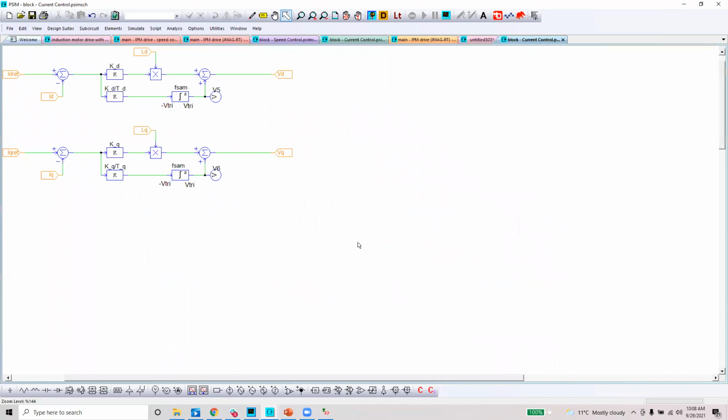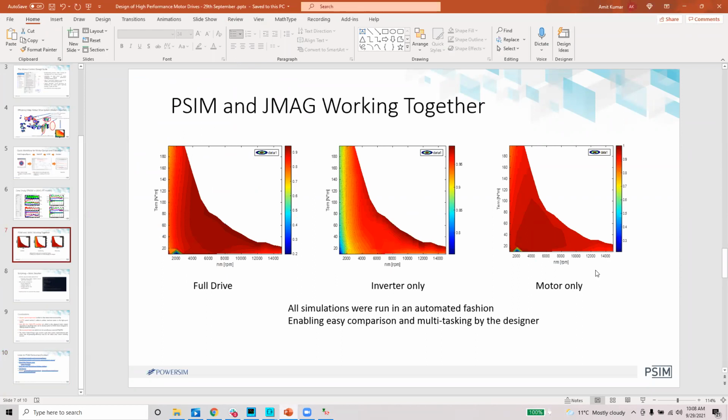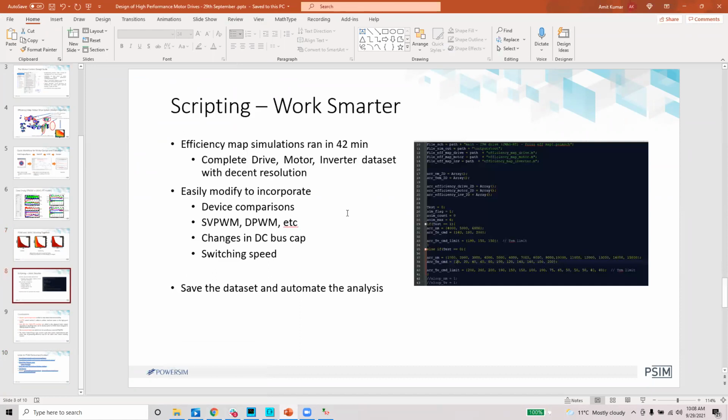Okay, thank you. And I have one last question from this person. Thank you very much, Jean-Michel, for your question. Is it possible to create an efficiency map picture with PSIM? Yeah, we did it with PSIM only. If you look at this particular result, we got it from PSIM only. This efficiency map, we got it for the inverter only, also for the full drive, also for the motor. And actually, I didn't run it live. We actually ran it for 42 minutes to generate this, and also some other automation there with different PWM schemes.